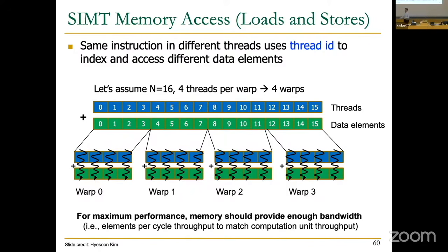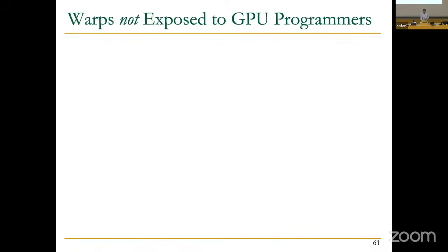If you have, I don't know, 32,000 add units or 32,000 load units in your GPU, what fraction of them can you actually supply data with? It's good to think about that. This is why the memory system is a huge bottleneck in these processors, because your computation bandwidth is huge. You can actually do a lot, but whether you can supply the data to those computation units becomes a problem. That's why we're going to dedicate the remaining 6 lectures to the memory system.